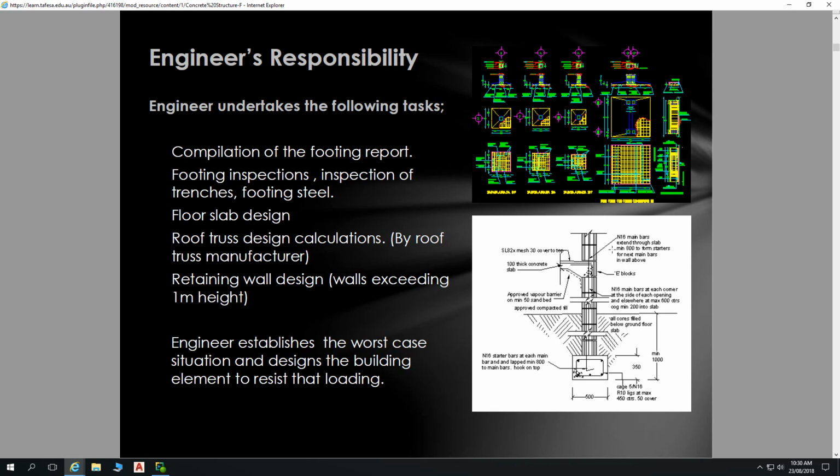Yeah, essentially, I can picture what you're talking about, because yes, there are certainly many pushing the envelope ideas, but the sort of stuff you're talking about may not be done very often in residential construction, where you get the sharing of steel from one element to another. It does happen, certainly in aspects like this, where we've got some core-filled concrete blocks, and it's got a reinforcing bar that comes down here, and it's got a cog on the end.